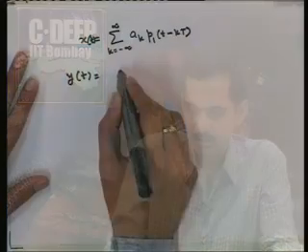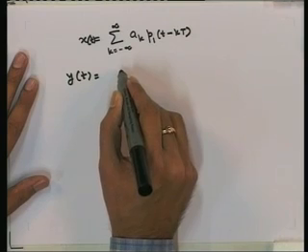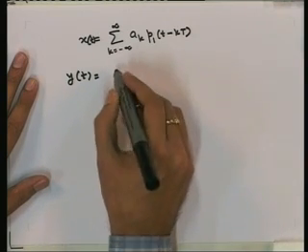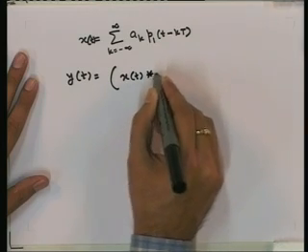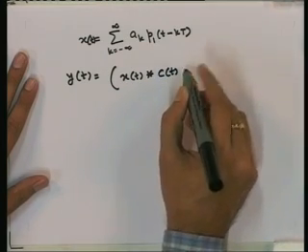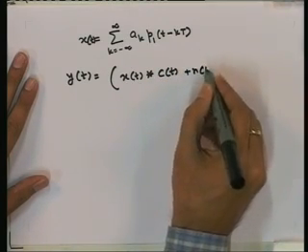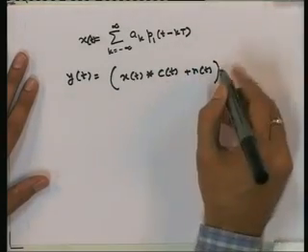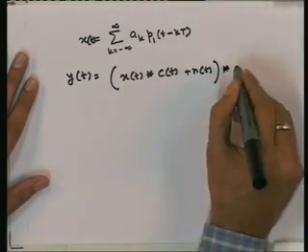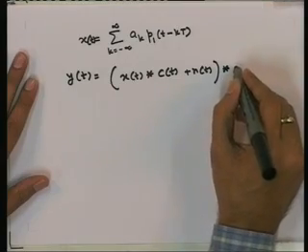So, Y(t) is the convolution of X(t) with the channel impulse response C(t), plus noise N(t), and then that is convolved with the receiver filter impulse response A(t).